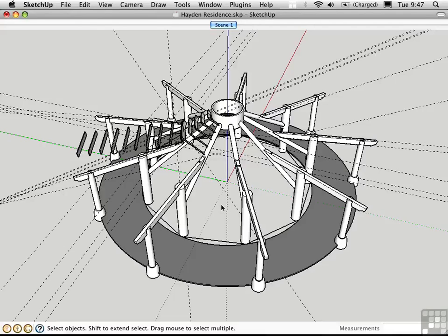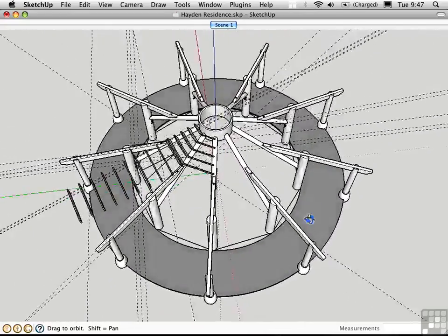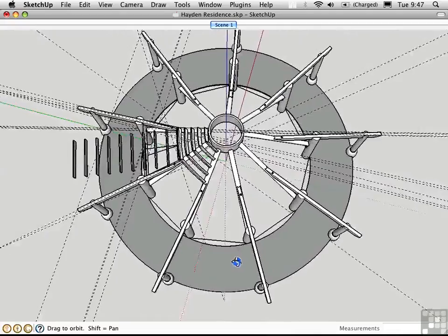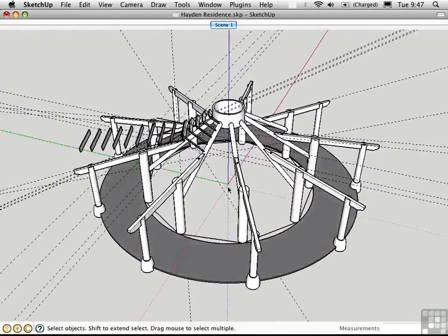Being able to change the drawing axes becomes of critical importance when you start to work with more complex geometry. Here I'm working with a 9-sided structure, and so I have some unusual angles to deal with. The drawing axes are represented by the red, green, and blue lines here forming a tripod. You can see that I've centered this within the design, and this is a good practice whenever you're dealing with a circular or regular polygonal structure to center it around the axes.